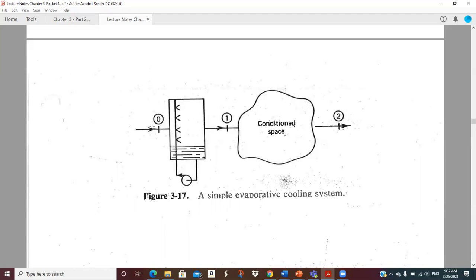And it's got nozzles, or a membrane, or somehow the air goes across that wet membrane. Basically we get evaporation, hopefully close to saturation coming out. It depends on the specs of the unit and how good it is. We're going to pick up moisture, and that evaporation process will cool the air down. So the dry bulb temperature will drop, but the moisture level will go up until we get to 1.